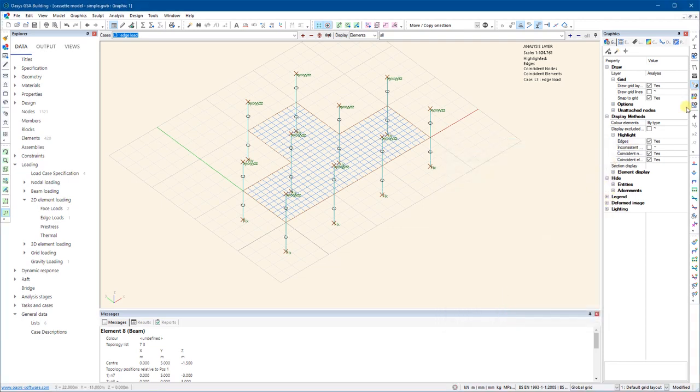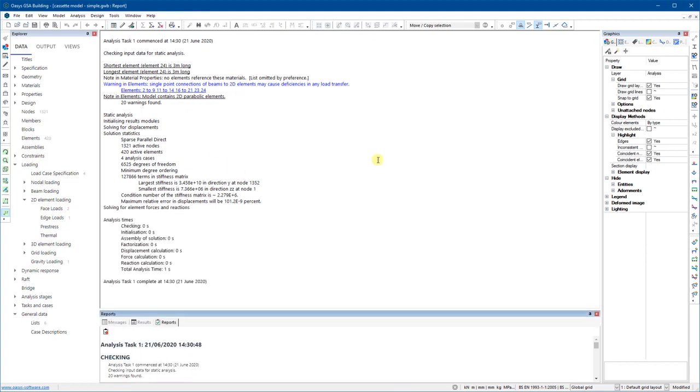I'll skip over these two for the moment and then come down. This is then, again, the quick annotation tools for displaying, as I showed you before, loads, deflections, bending moment diagrams once you've analyzed your structure, and so on. If you only want to annotate a particular set of selected elements, that's the button you would press there. For 2D elements, and if I just quickly run the analysis for this.